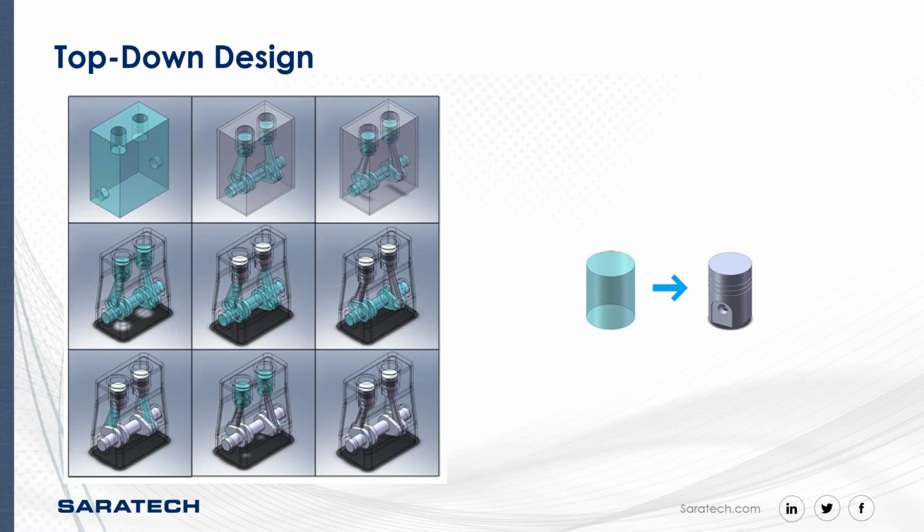And if we move down this block here, we can see the detail design being driven by those requirements, right? So at any point, if the volume changes at the skeleton or at the top level, your detail parts should be updated and that should be reflected, okay?